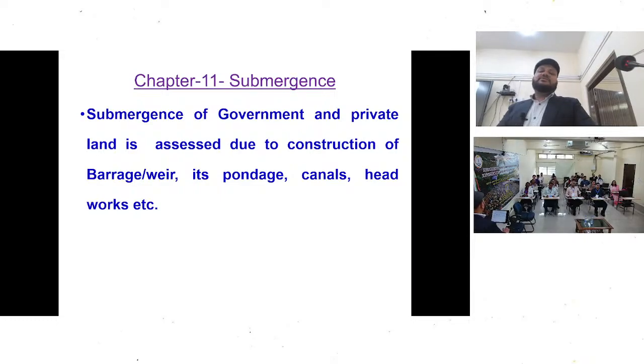Then submergence. If any area is submerged, then we have to look into this issue also, because in Arunachal the cost of projects is very high only due to submergence, because all lands belong to people there. But in other areas, forest belongs to the government, so there is no compensation. But I have seen a lot of meetings. I was in the ministry when around 50% of the cost was land compensation. Then we have to plan accordingly.